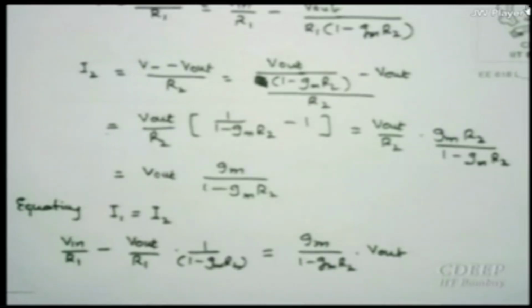Okay. So yesterday I was telling that under certain conditions only OTAs behave like good voltage controlled voltage sources. The condition I will now bring up. What could be the condition? Anyone, quickly? Gm R should be very, very high compared to 1, which many times you can always attain in an OTA. That's the purpose of an OTA, Gm is higher. So if you don't use very small R's, then Gm R will be very large compared to 1, and then the equations will be the same as the op-amp requirements. Is that okay, everyone?